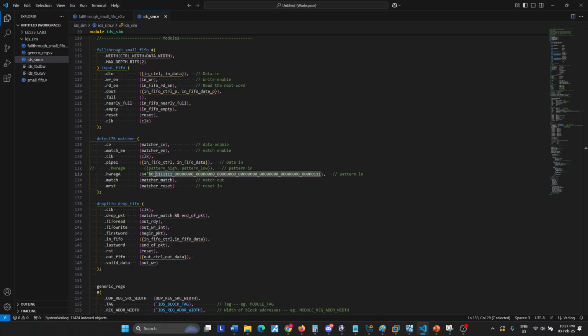A mask of 7 bits is used to decide which byte of the pattern will be compared with the input data stream. So essentially the MSB will match the upper byte of the pattern with the upper byte of the incoming data. The second bit will say that the second byte from the MSB is going to be matched with the second byte of the input data. So each bit corresponds to checking that particular byte from the pattern in the input data.